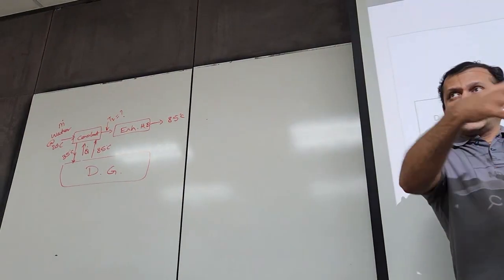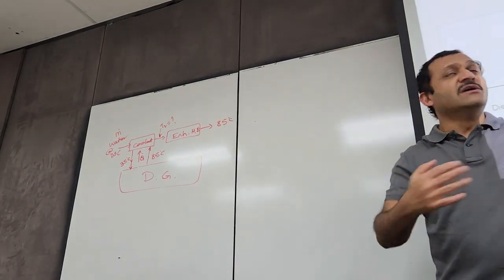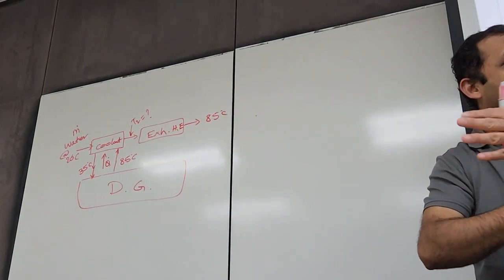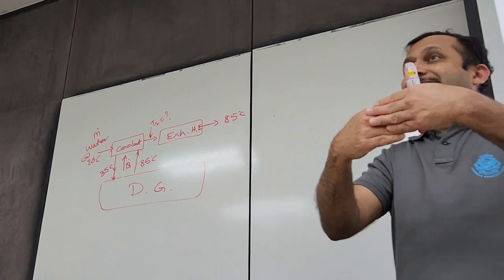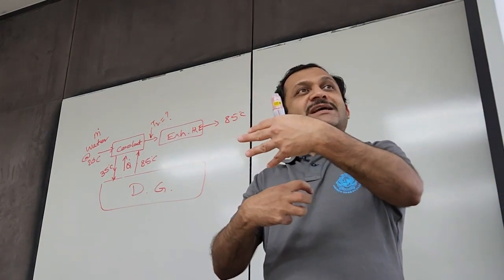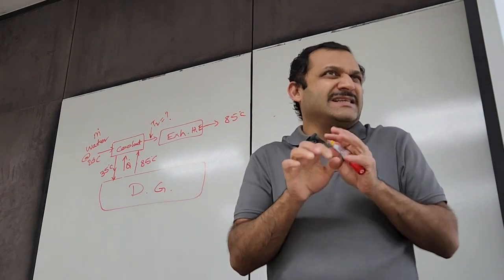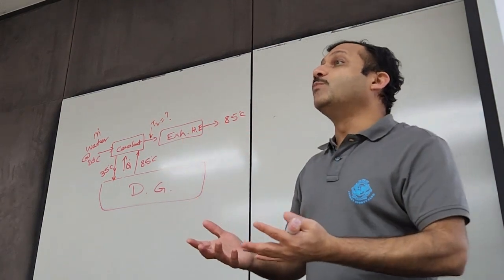So you've got a heat exchanger, hot coolant is flowing through the heat exchanger and cold water is flowing. They're transferring thermal energy between them. What we are saying is whatever thermal energy the coolant loses is received by water. That's to simplify, and that's how you start your analysis whenever you're doing modeling.